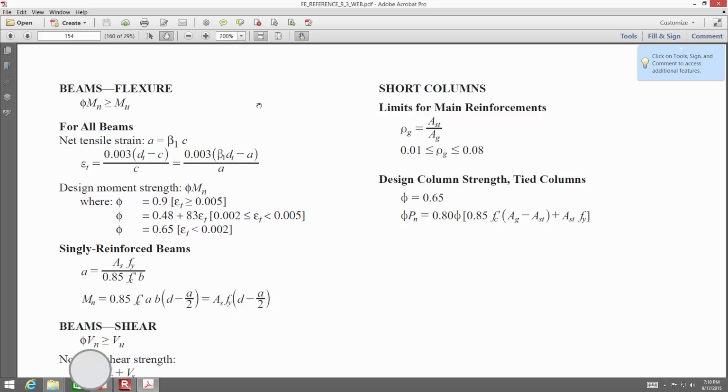One other piece of advice that I would give you is that when it comes to beams, it's probably unlikely that you're going to be doing heavy design. If you remember from concrete design, if you're designing a beam, it's a highly iterative process. You're making guesses at the beginning, guess the beam's about this deep and about this wide, and then from there you have a weight that gives you a dead load and you go from there.